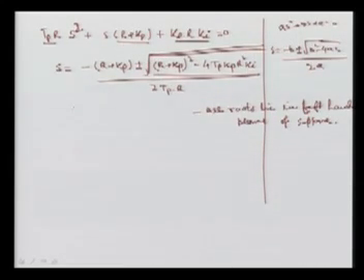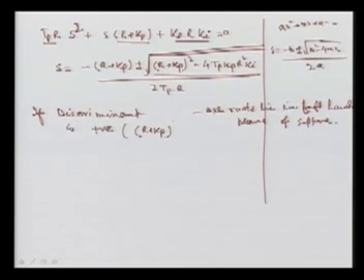If the discriminant is positive, in that case (R plus Kp) square will be greater than 4 Tp Kp R square into Ki. So this is positive, and this shows that we are getting a non-oscillatory damped response.